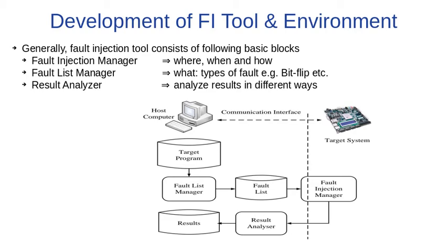The fault injection manager is a critical component which is responsible for answering the three basic questions of the fault injection technique. Where to inject the fault, meaning the location of the fault. When to activate the injected fault, meaning the timing of the fault. And how to inject faults, meaning the method or technique used to inject the fault in the system.